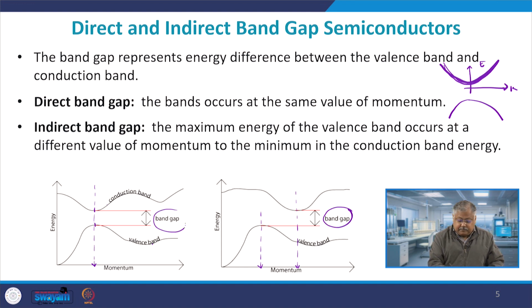So, if, for example, in the first case, in the direct band gap material, the electron has to travel from the conduction band to the valence band, it releases an energy, but that happens with just a change in energy; there is no change in the momentum space. You get the point, which means that its velocity effectively remains the same, but the kinetic energy falls from a high value to a low value, and there is a recombination taking place between electron and hole.